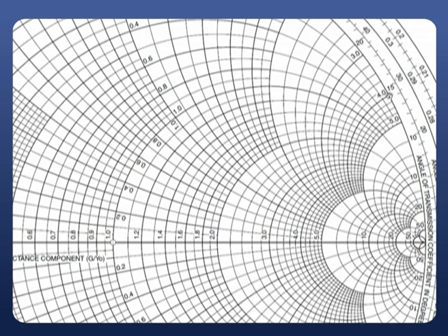Now it is plus 4, right? Highlight this plus 4 circle. Now the intersection point of our R is equals to 2 circle, that is nothing but this highlighted circle, and X is equals to plus 4 circle, that is exactly this point. So the point that I am mentioning is nothing but the load impedance. And once again, clearly remember, this load impedance is the normalized load impedance.